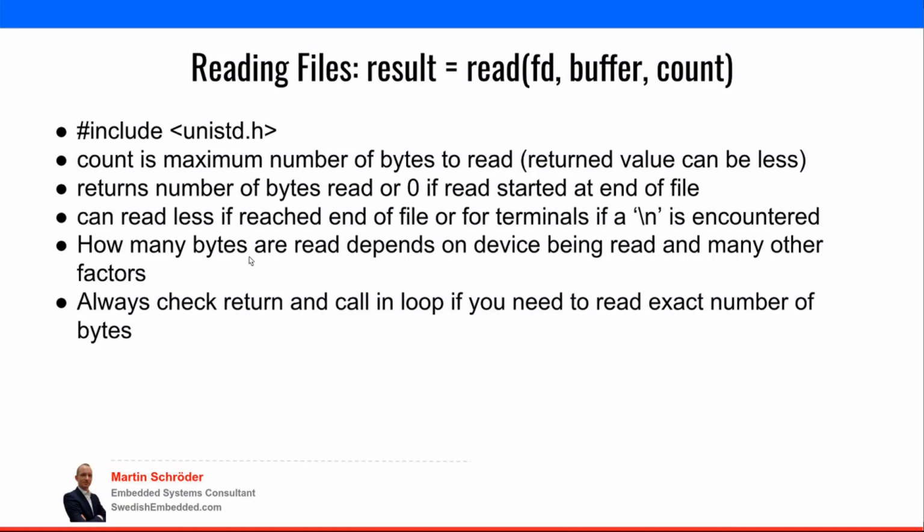Now, it can return less than the number of bytes you specified, and there's a variety of reasons for that. For example, if you're reading from a UART, the number of bytes would depend on the terminal settings you've configured, but you will get the number of bytes that are available for reading. If you're reading at the end of file, you will get the number of bytes you are able to read from the file, but not anything else because you reached the end of file. So it can return less, and it often does return less. So you have to always check the return value and make sure that you've read the number of bytes that you've intended to read.